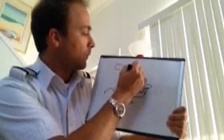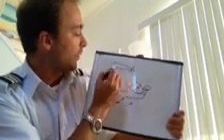Another thing is called the Frise aileron. The Frise aileron, from looking at a cutaway view, is an aileron that's hinged offset. So when the aileron is deflected up, the leading edge of the aileron is dropped into the relative wind, causing drag, which would be on this aileron here, and thus also causing that yawing moment, helping the airplane to turn in the desired direction.